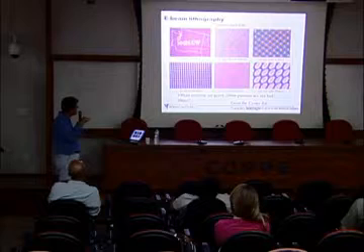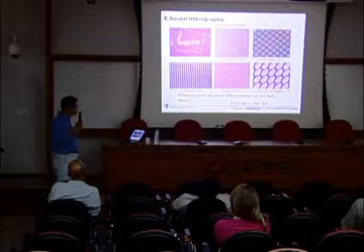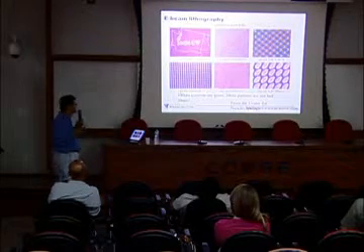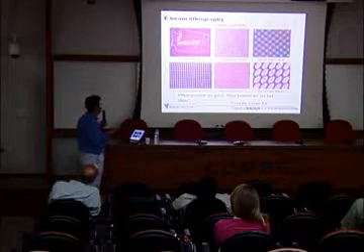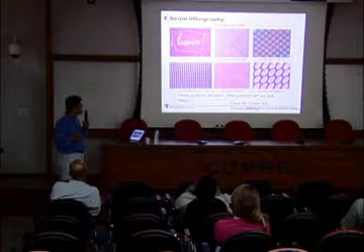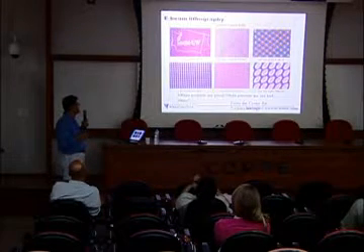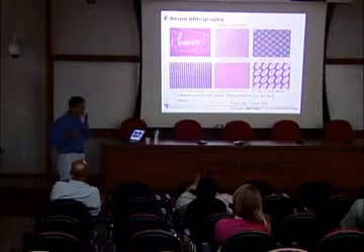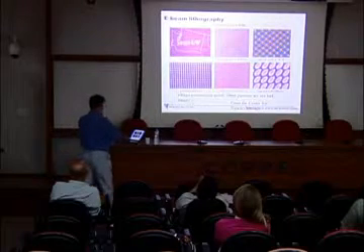If you want to pattern a 100 millimeter by 100 millimeter wafer, then it takes about 10 hours, because it's a serial process. The electron beam should draw all the patterns, but it's being improved. Very recent electron microscopes cost a few million dollars. They can make these patterns within about 10 hours. That's the state of the art.